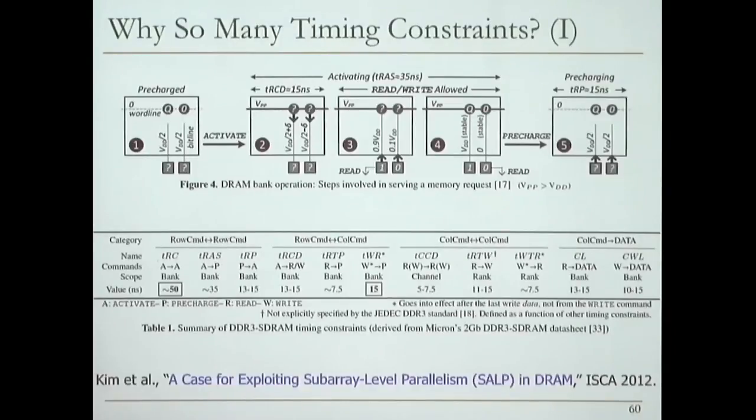But the problem is now you have a different protocol, and you need to have a handshake. As opposed to relying on agreed-upon latencies, that asynchronous protocol leads to some other overheads to ensure that you actually get it correct. So there's another problem. That's why we have synchronous DRAM. But that asynchronous approach, if you can design it well without a lot of bugs, could actually be better.